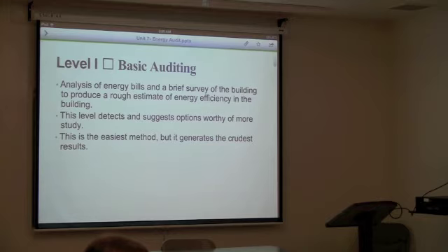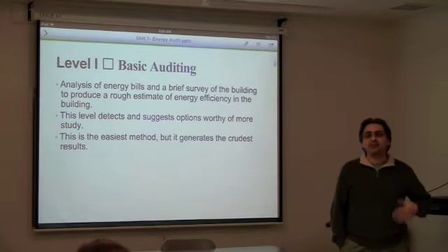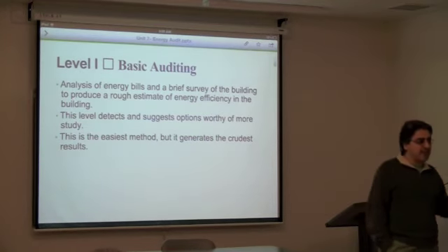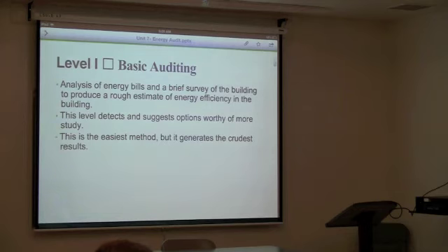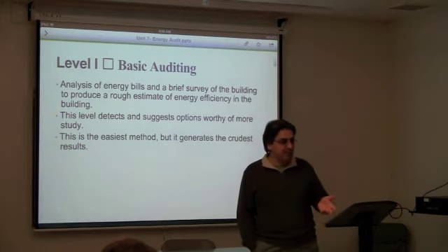The reason that you need to create this pattern is, you're not going to believe how many problems factories or residential places or commercial places have because their meters are not working correctly. You cannot assume and start your energy auditing based on meters that are not correct. By trying to establish a pattern, you're actually double checking if the meter is taking measurement correctly. Right? You might say, what do you mean by meter not being correct? Because if the meter is not correct, you are paying based on that meter monthly.